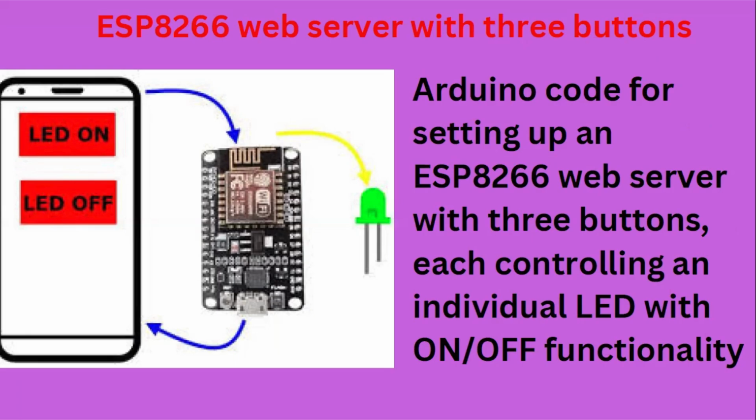Arduino codes for setting up an ESP8266 web server with 3 buttons. That is our project. Each controlling an individual LED with on and off functionality. That is, we are controlling 3 LEDs. We are connecting 3 LEDs. But in this case, I'm using an RGB LED. A single LED which has 3 points, or rather 4 points. One will be supply and 3 will be ground. So those 3 colors will use only a single LED. That also we can do it. Of course, we can use separate LEDs also. Okay, and we'll control those LEDs on off.